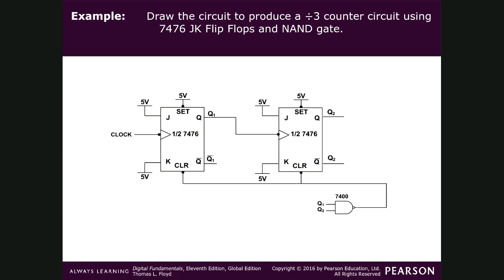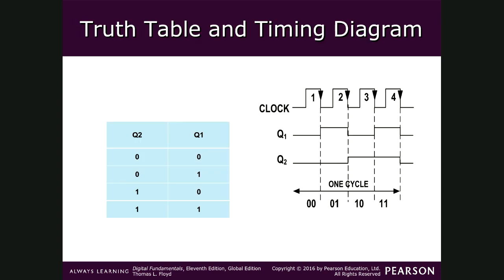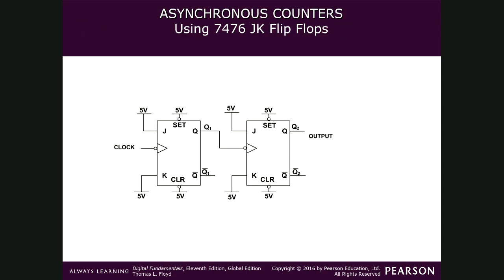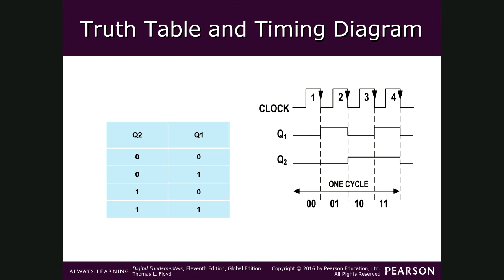Huh? Okay, counter. So counter here, for example, what is this one? This is an asynchronous counter using JK flip-flop. So this is 2 flip-flops. So it is a mod 4 counter. Okay, 0 0, 0 1, 1 0, 1 1. So see here, I will tell you.